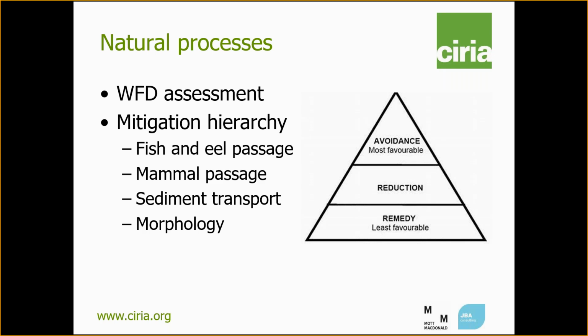For mammal passage, benching or a separate dry culvert are preferable to a raised shelf, which is undesirable and should be retrofitted as a last resort.